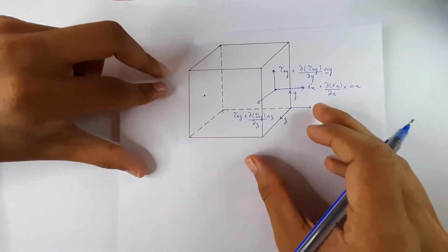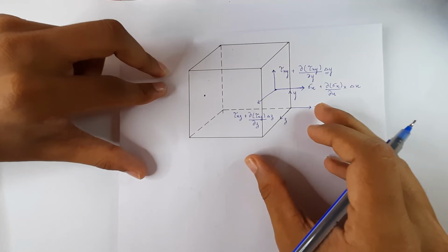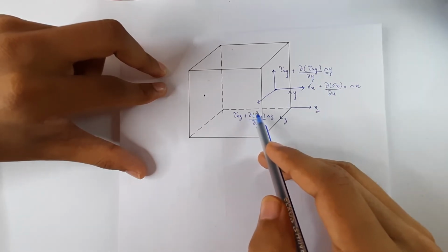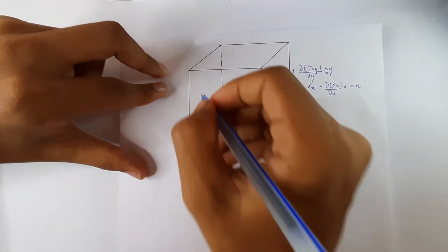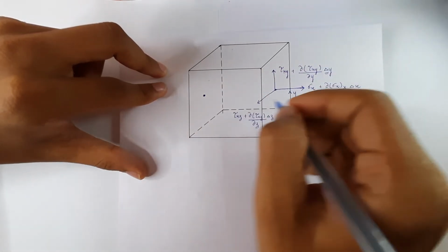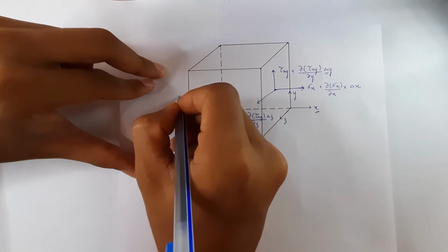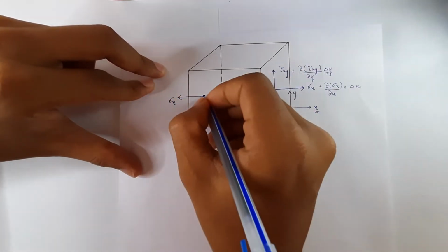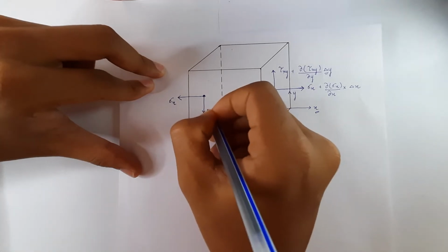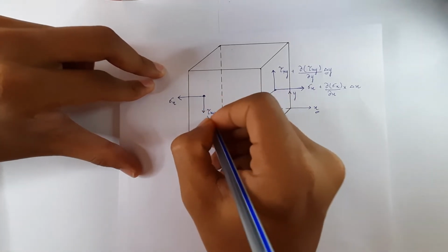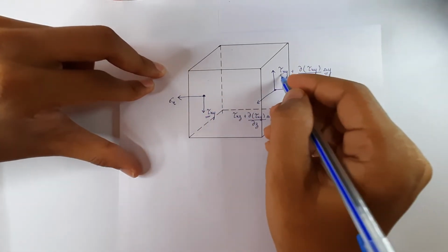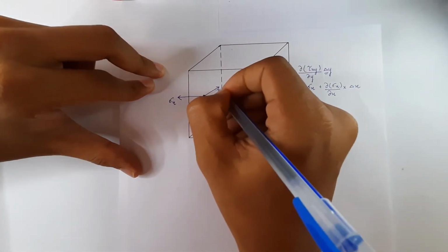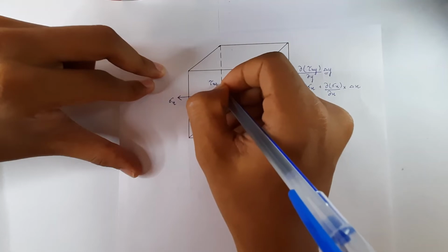These are the values of the shear stress which we have written on the basis of the stress gradient formula, and corresponding to this, there will be shear stress in the opposite direction for each component. So this will be tau xy. Take a look, this is in the opposite direction of this expansion. Similarly, the z will be like this, tau xz.